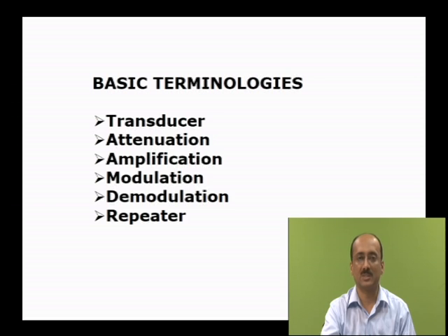Modulation and demodulation are two essential components of communication. Modulation is a process wherein some feature of a high frequency carrier wave is altered in accordance with the instantaneous value of the message signal. Once you do that, it is something like you are coding your information. It will not be directly available to the user. You have to demodulate it, decode it. So demodulation is a process wherein you detect that signal, retrieve the essential component, the message signal, and leave the high frequency carrier wave.